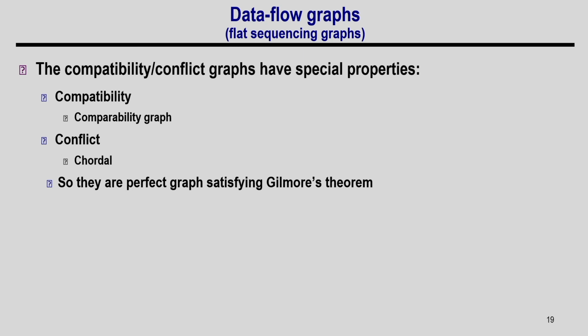So, now let us go back to our data flow graph. If you remember, for the scheduling we took one basic block at a time and then tried to schedule the behavior. But in general, now if you try to solve this allocation and binding problem for a particular basic block, we will show that that particular graph is actually nothing but an interval graph. Okay.